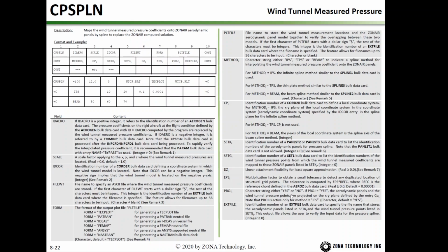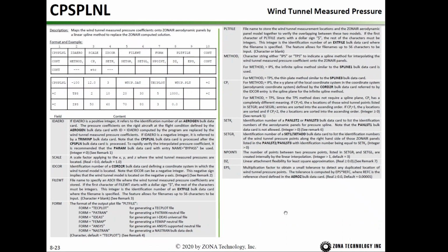PROJ is projection. If yes, all the aerodynamic panels and the wind tunnel pressure points are projected to the XY plane defined by this coordinate card, and then this projection file can be saved here.